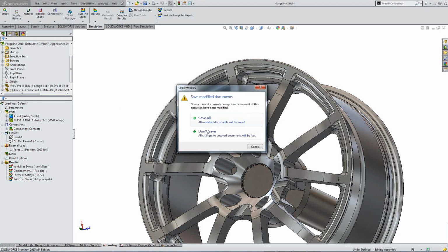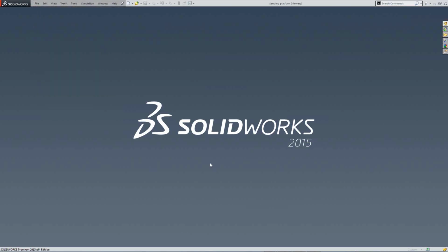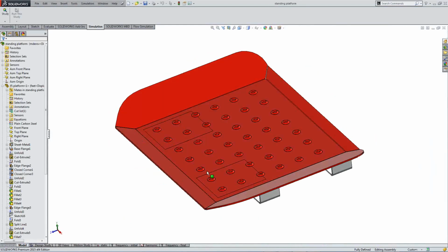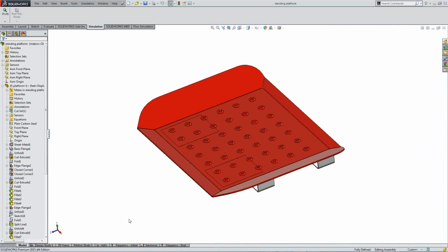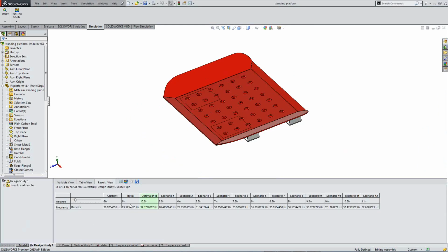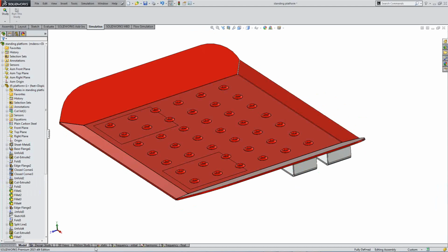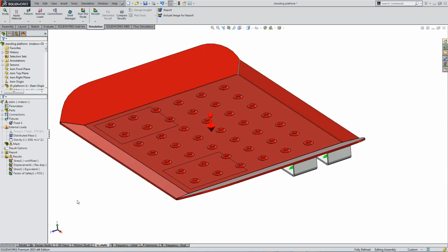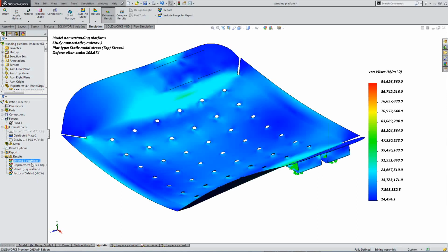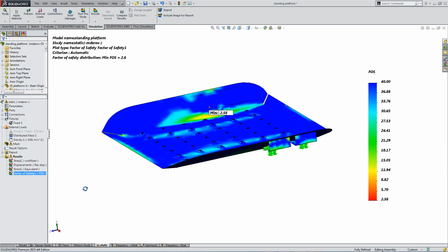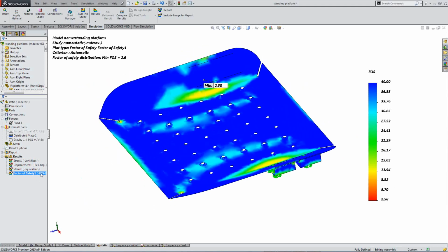So I'm going to go ahead and quickly show you that model. I don't want this to be a death by PowerPoint. So here's the platform, and we can see that the brackets, this is actually the optimal design. So let's switch this to the initial design. You can see that when we start up the initial design iteration process, the two brackets are next to each other, and the results of that, in terms of strength, we're looking at stress analysis, the stress results, displacement results, factor of safety. It's about 2.58, like we saw before.